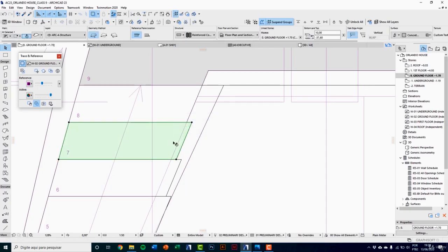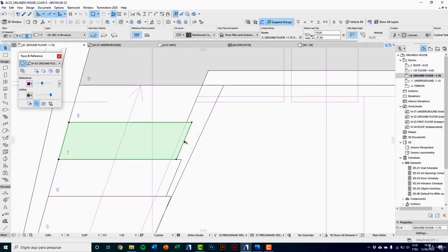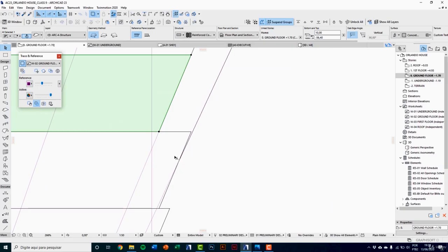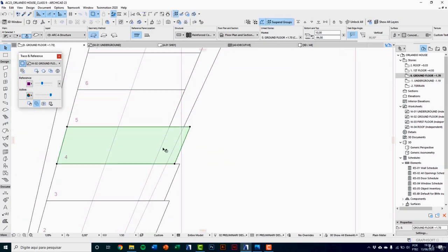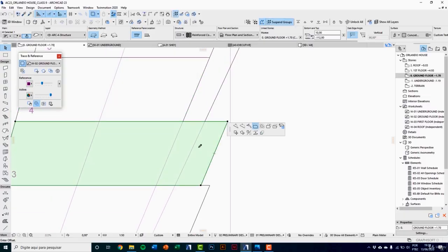So I'll press ESC to retire selection and clicking here at the edge, in the floating palette, I'll choose Offset Add and do the same. I'll do the same thing for all treads. You can use as reference this black pencil or perpendicular sign.